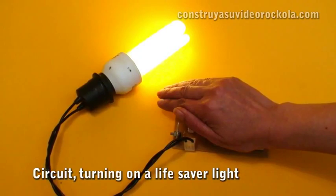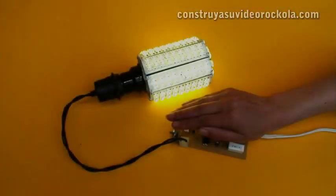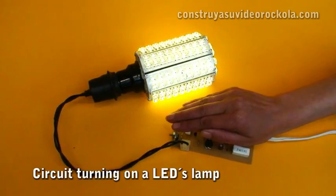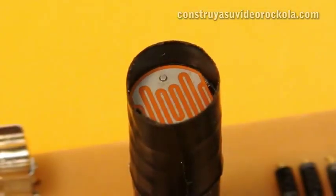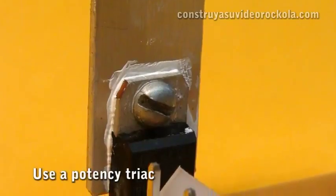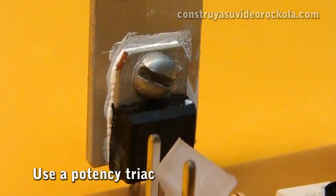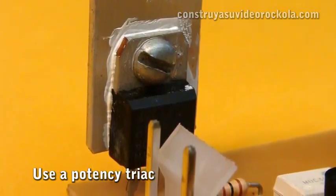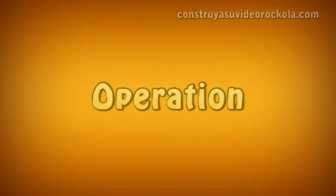This circuit operates with voltage from 115 to 220 volts, no need to make any changes. You can light a bulb up to 100 watts. If you want more powerful lighting devices, you should only change the BT136 triac for one that supports more amps, such as the BTA06-600, which supports up to 8 amps.